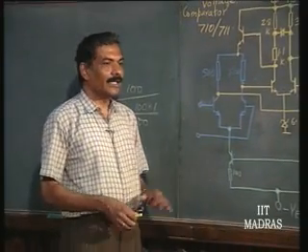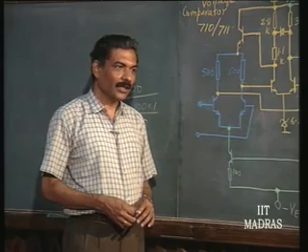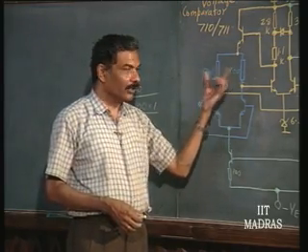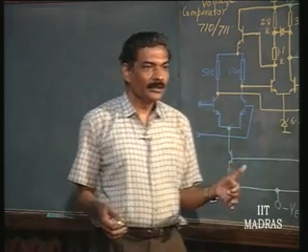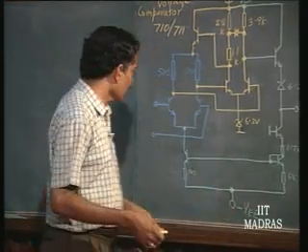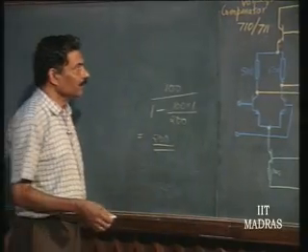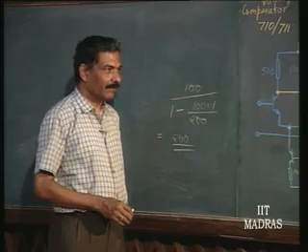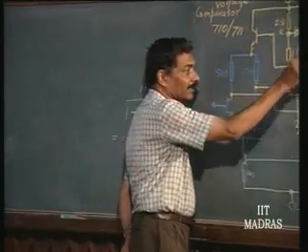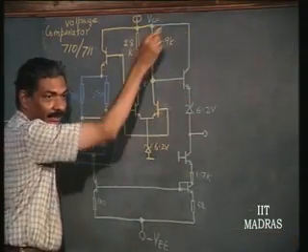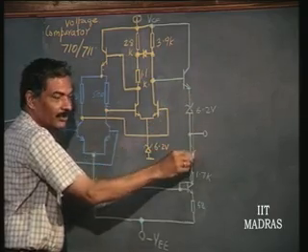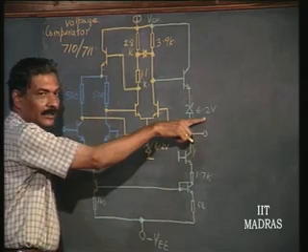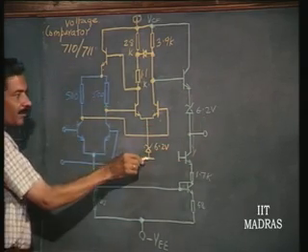So, we know that gain is not very important in the case of comparators primarily, okay, and therefore, we live with low gain in order to boost up the speed of operation and then give positive feedback here in order to increase the gain to the original value restored. Now, from here it is connected to again common collector output stage. This is of course biased properly, and there is a level shifting arrangement here 6.2 volts once again, okay. You can check this, this is 6.2 volts.